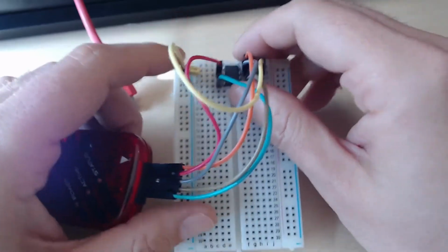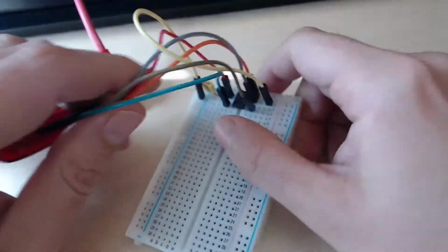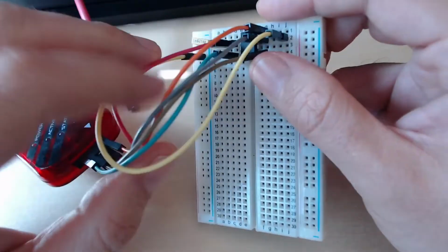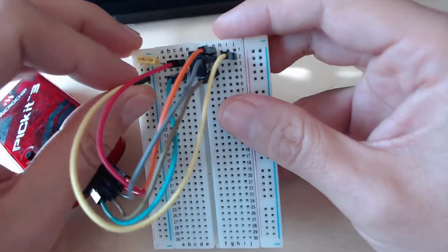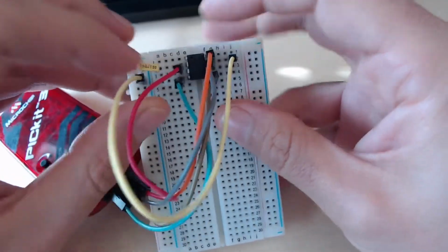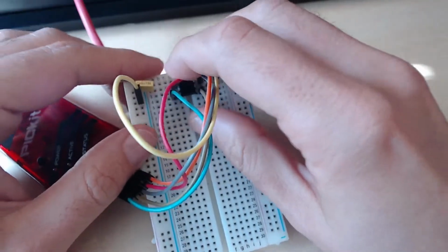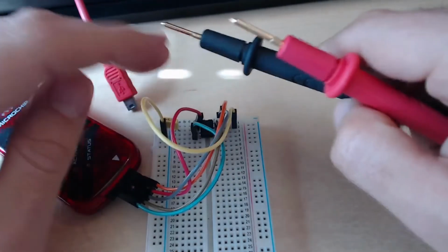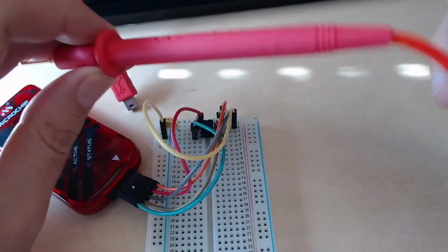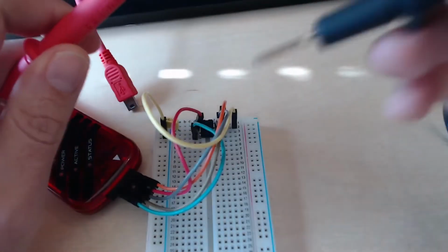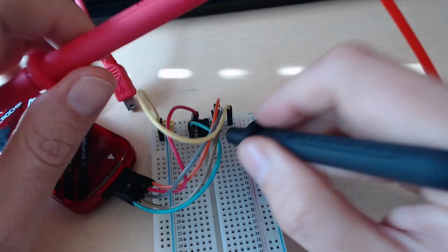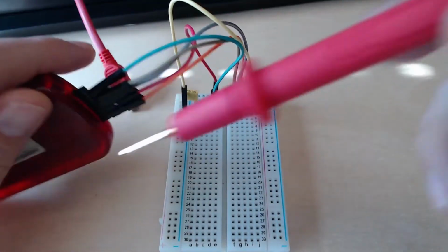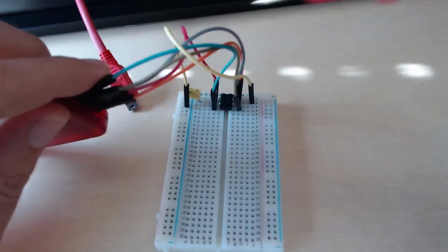And the second thing that you need to do, if you're working on a breadboard with jumper wires like this, is remember that these jumper wires, especially the cheaper ones, don't age quite well, and they might have all sorts of connection issues. So what you can do is just get in there with your multimeter and do some continuity checks between the pins of your micro and the pins that you are connected to on the PICKIT3. Make sure that none of these are broken.